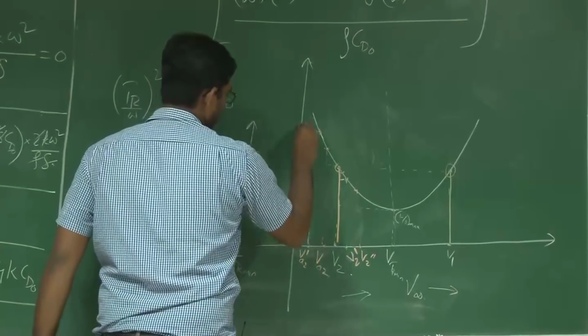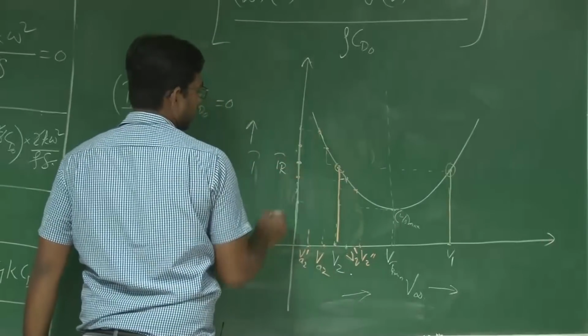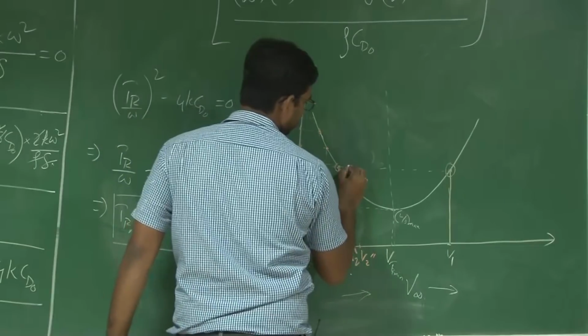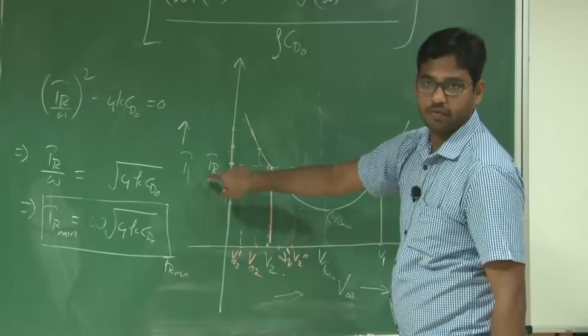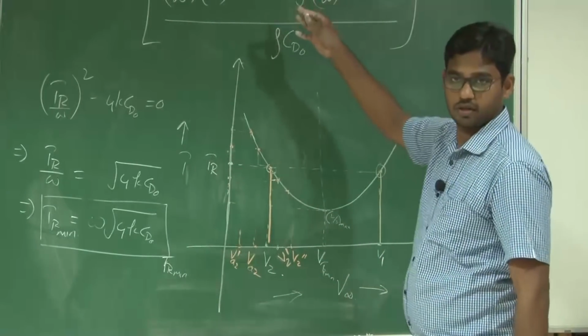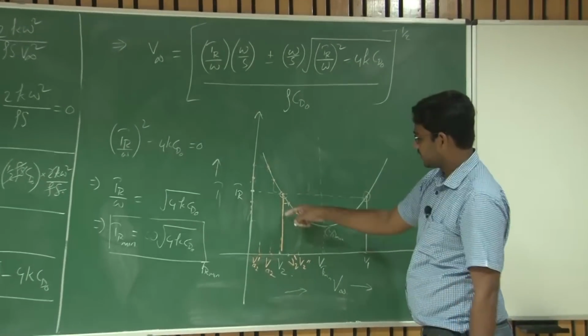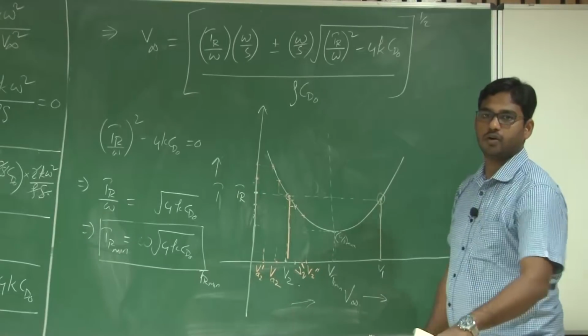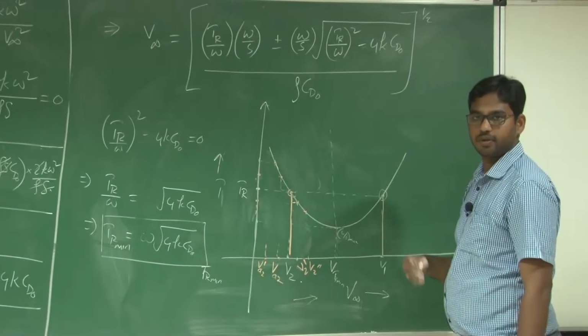Say this is the point of my interest, thrust required at this particular location. So I can achieve this level flight either by flying V2 or V1. Now we understood if I fly at V2, I need to give a constant correction. It can't come back to its equilibrium by itself.